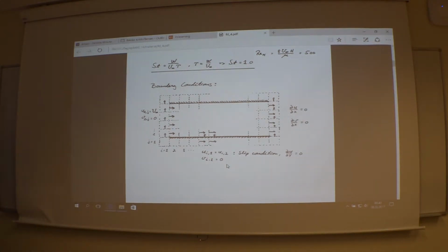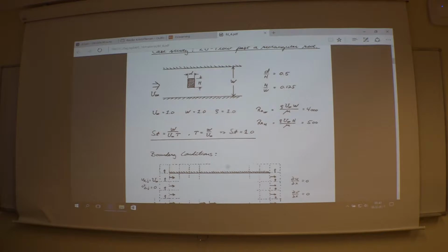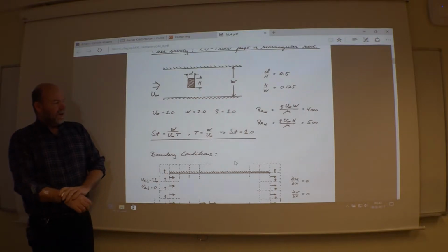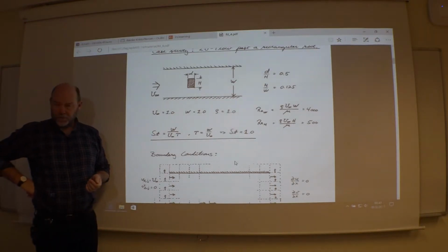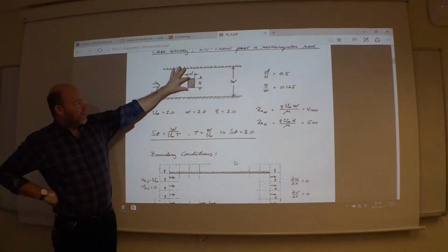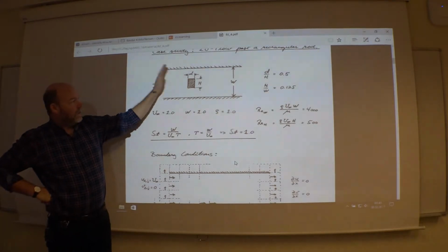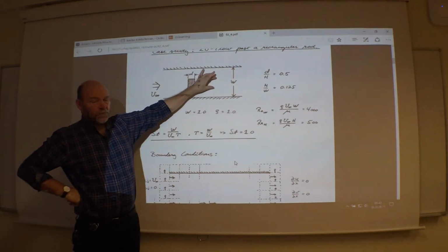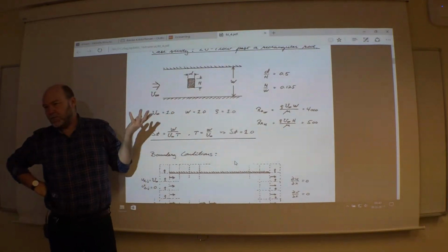Initially then, we start with everything equal to 0, which might be a bad idea, because we are going to search for a laminar solution here, which is time dependent, and it might take some time to sort of establish it. So if you have a completely symmetric setup here, this block is in the center, everything is symmetric around this line, then you risk getting a symmetric solution, which is actually also a solution to the Navier-Stokes.